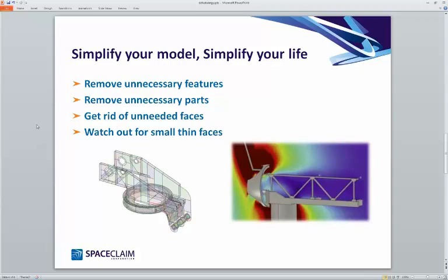And also, of course, if you're doing an assembly level analysis, most of the time, again, there are exceptions, but most of the time you don't need to have every little last bolt in the model for your analysis of your mesh. I mean, that can just add hundreds of thousands of nodes and elements that can really bog the whole thing down. And what this defeaturing will do, what this simplification will do, is it will make it a lot easier for you to do more runtimes, figure out more solutions, tweak models, make suggestions back to the design team, and really converge on the best design or a better design much faster.